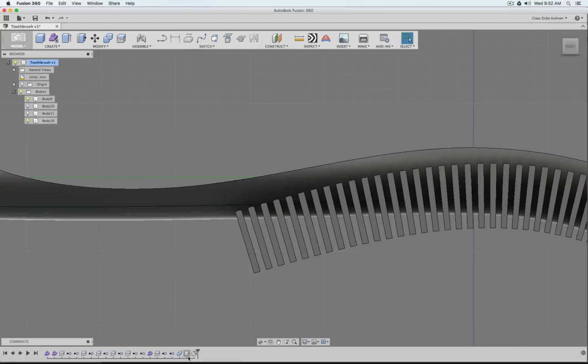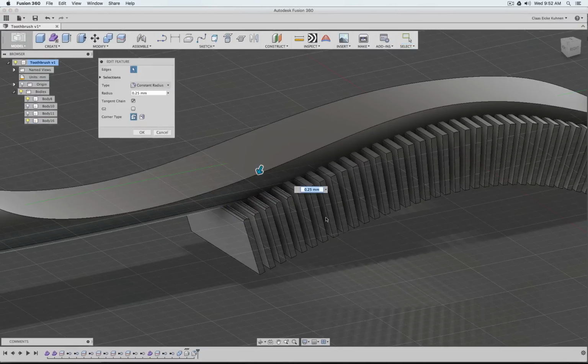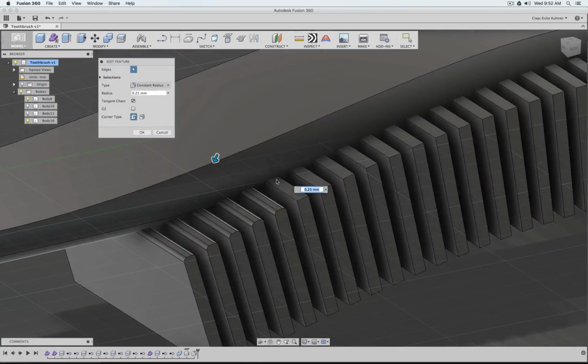So you see now we inserted a new base feature, so the geometry, and then at the end result there we can select these edges and give them a fillet. This is actually similar to the edge weight in Blender when we tell the bevel command not to bevel the complete object but certain edges. Also here, when you hold on a Mac the Apple key, or I think on Windows the control key, then we can add or even remove edges. But there's no weight, so 1 to 0 is just bevel it or do not bevel it.